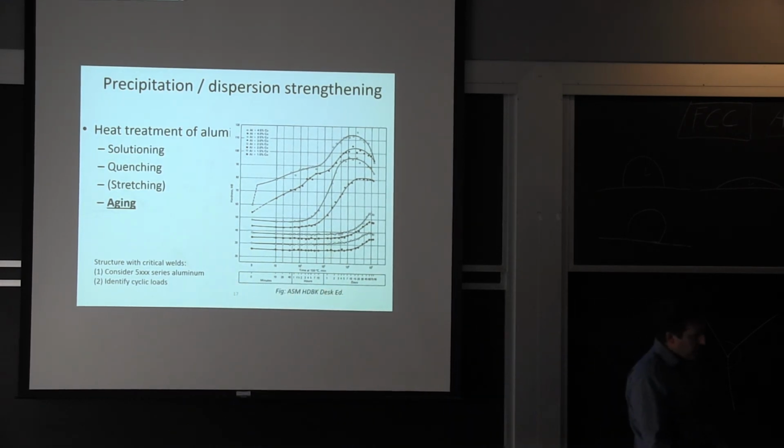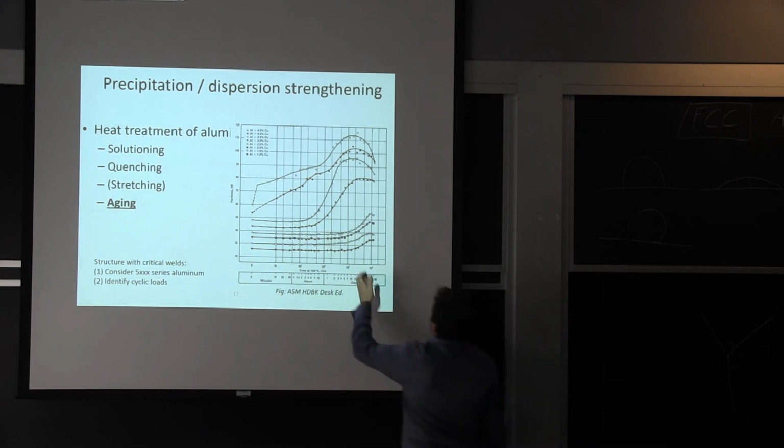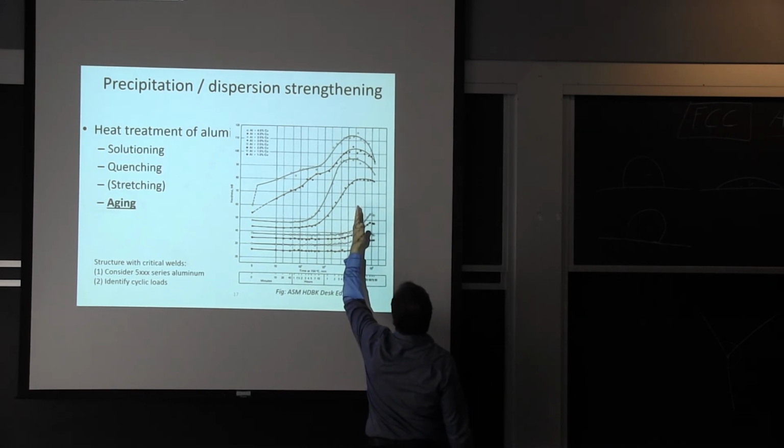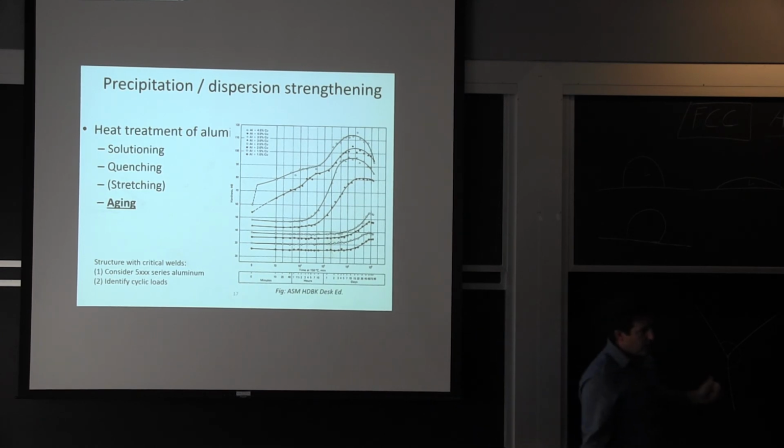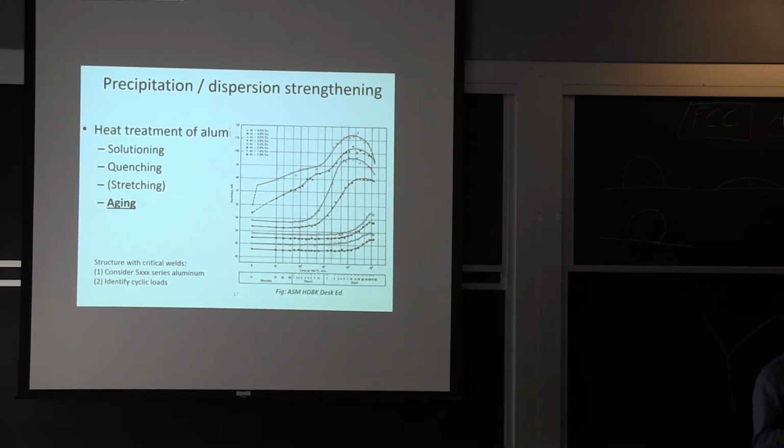If you're looking for the best ductility you can think of, lots of times you're going to try to be at the peak or sometimes a little bit before the peak. And what happens there is we know we have the smaller particles, so they're going to interact with the dislocation in a different way. They actually create more hardening. More particles, more hardening. Think of it that way.